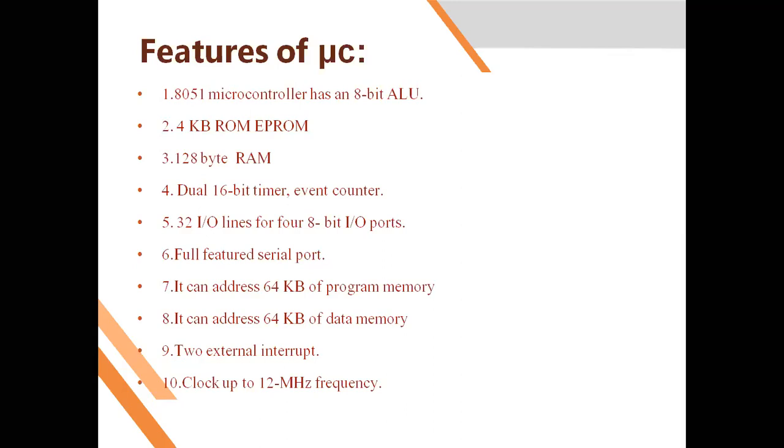Okay, so at this moment only remember that it supports 2 timers. Now each timer is of size 16 bit, and what is the name of the timers? T0 and T1. Now see here, it is having 32 IO pins. Now why are IO pins important? Because through that pin we can give the input to the system, and through that pin only we can take the output from the system.